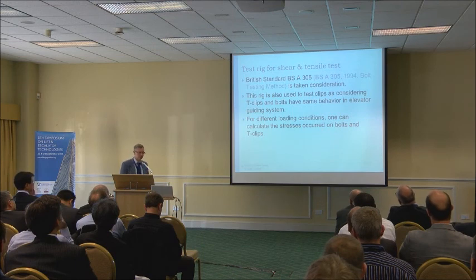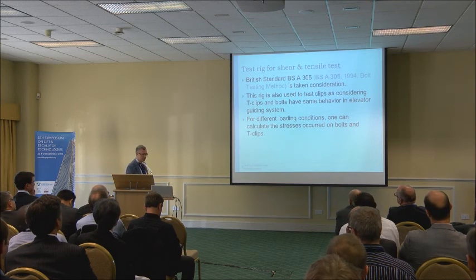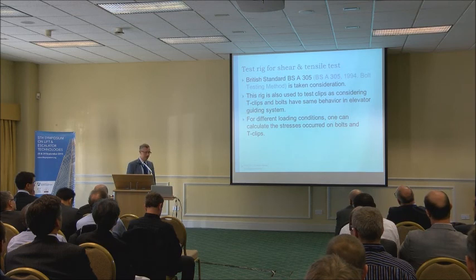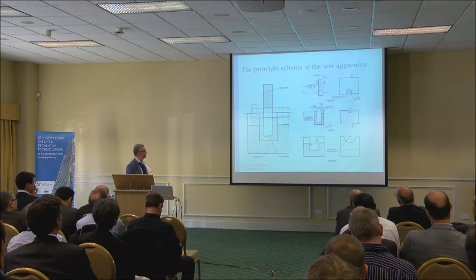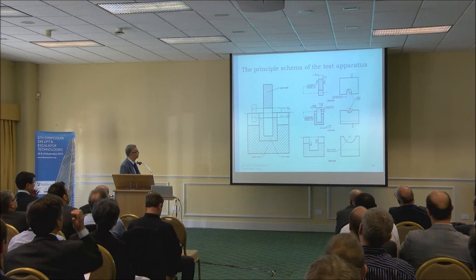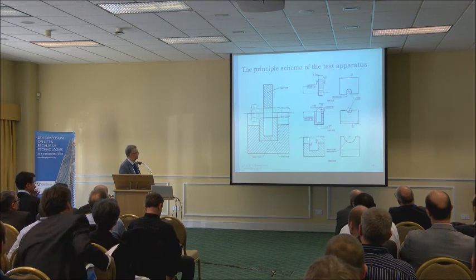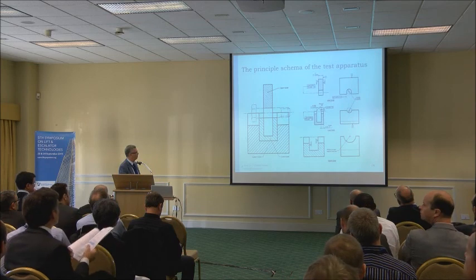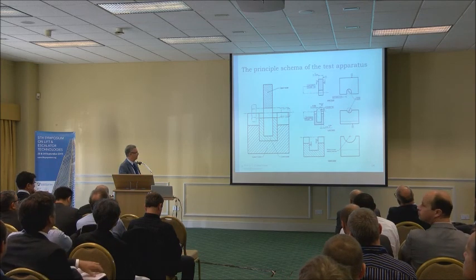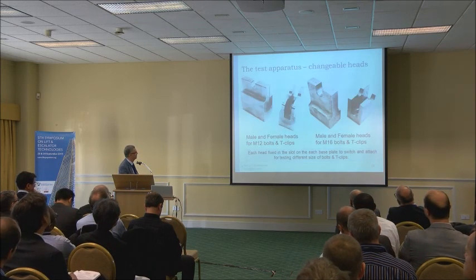We found one British standard related to a test rig for shear and tensile tests. Then we adapted it for our work and used this principle for the test apparatus. So we placed either a bolt or a T-clip here, and then we press it.